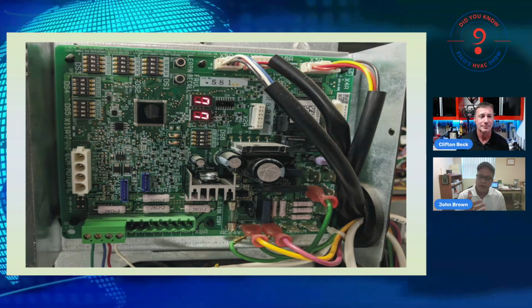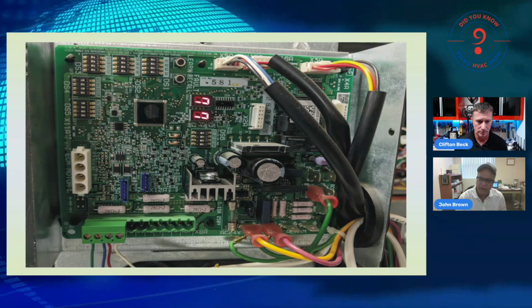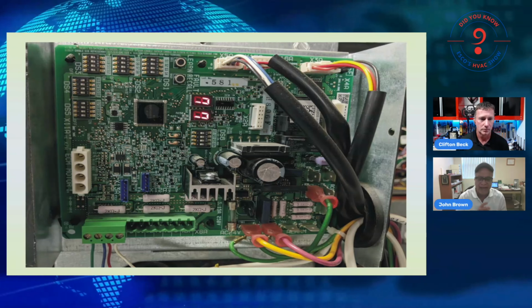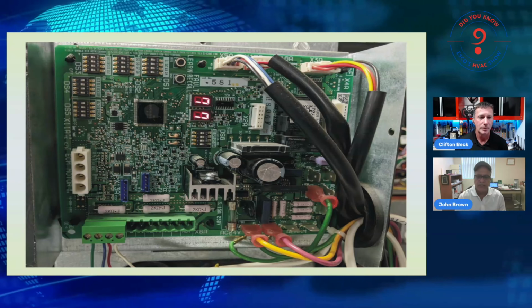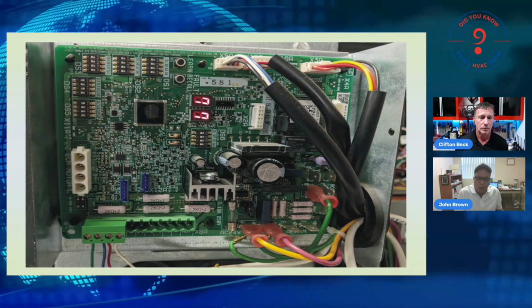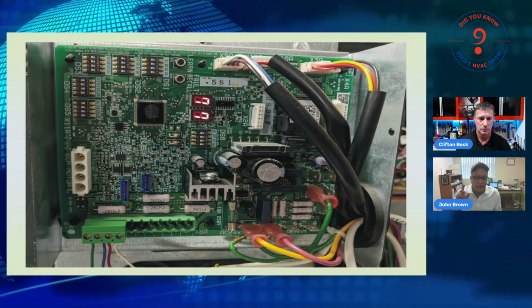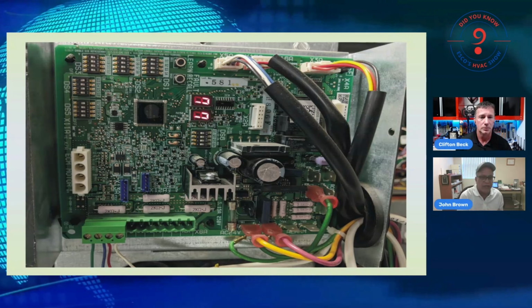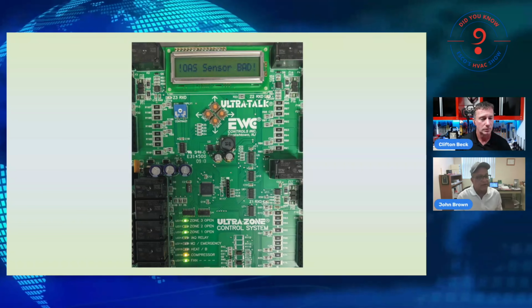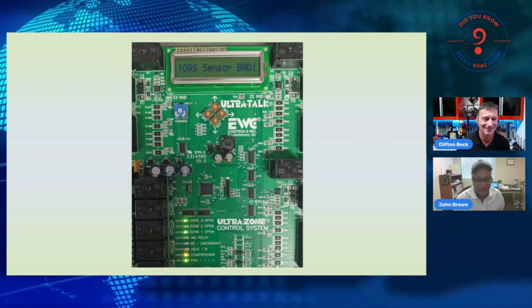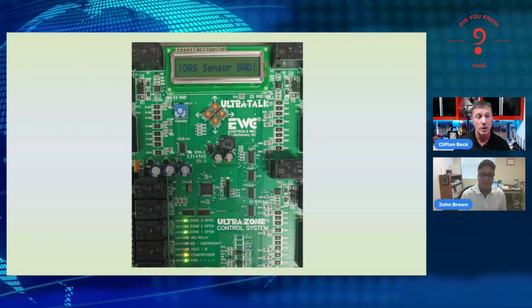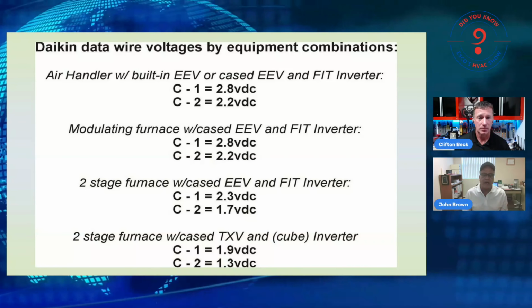Here's a shot of the EEV board. E77 means I can't configure the network. I can't talk to the outdoor unit, so I don't see a complete system. This is a clue. The zone board might see the air handler, it might see the furnace, but it can't see the outdoor unit if it displays OAS bad. Believe it or not, I've had guys tell me, I replaced the sensor. It's still not the sensor. It's the data wires going outside. The network has not configured.